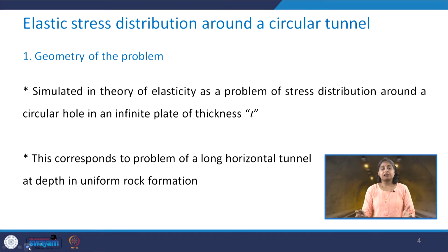Now, this geometry is simulated in the theory of elasticity as a problem of stress distribution around a circular hole in an infinite plate of thickness T. Basically, we have the solution of such a problem in theory of elasticity.